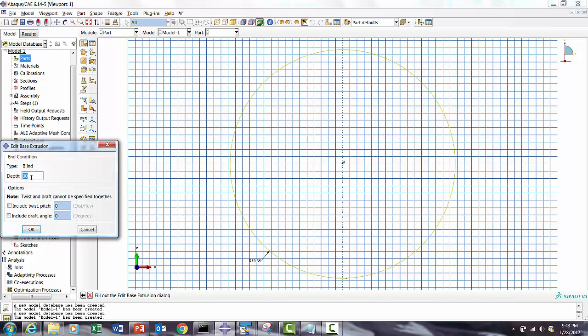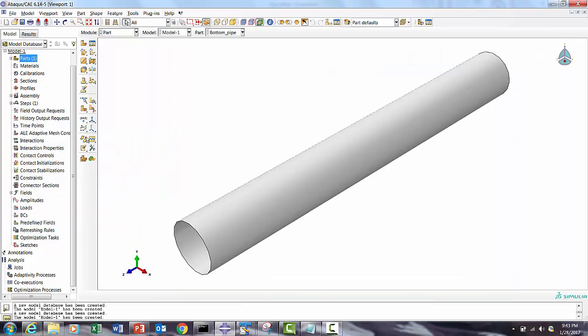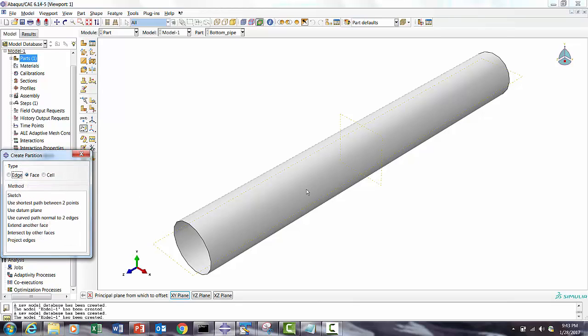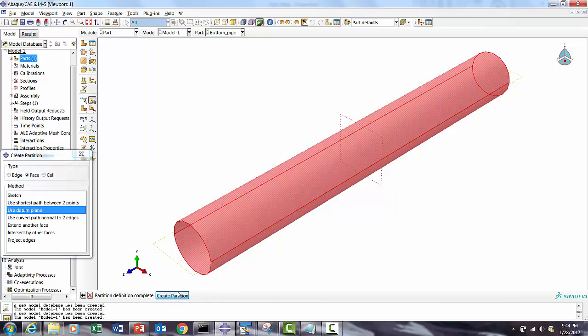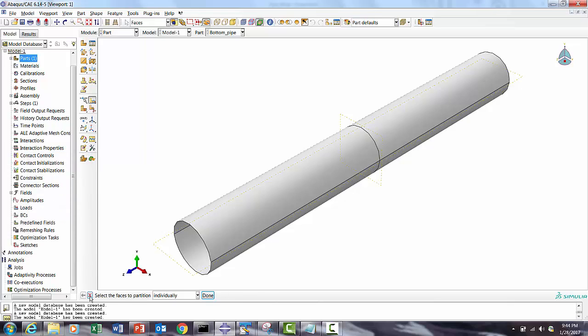Now we'll extrude it by 1270. I'll cut this along the length at the half, and the center also I'll cut. So I'm going to put XY at the mid plane, so mid center. 635 is the mid. Total is 1270, so half will be 635. Then I'll also put one plane XZ at 0 0. So that's done. Then I'll quickly cut it. I want to select this, so it is half. Then I'll select both, and then select this and trim it. That way it is better for me to put the mesh and then create a pin condition and rotational velocity. That's the reason I cut it.